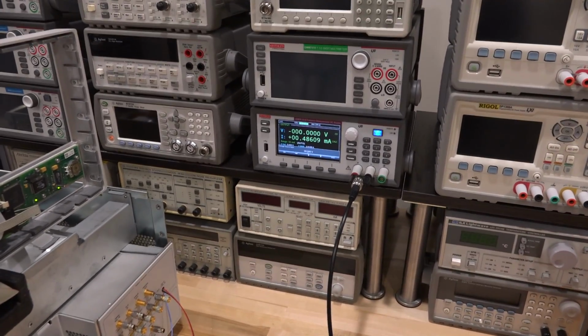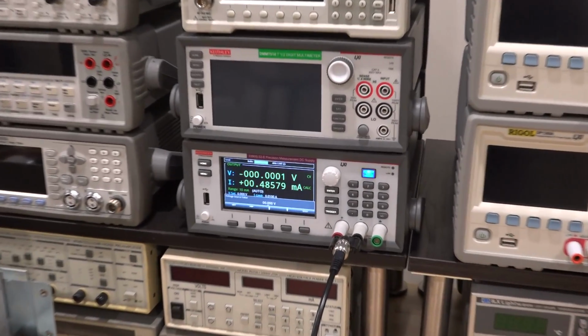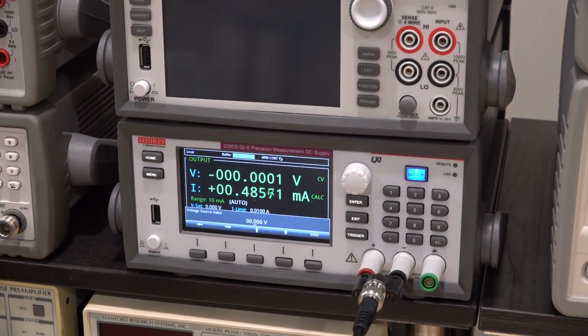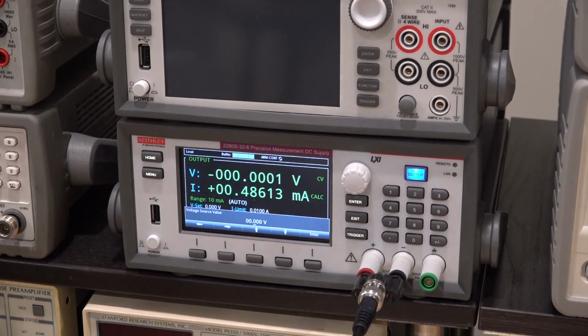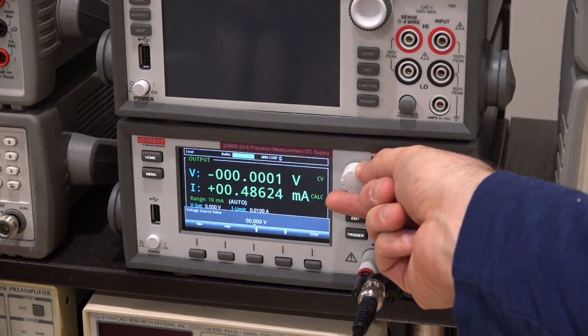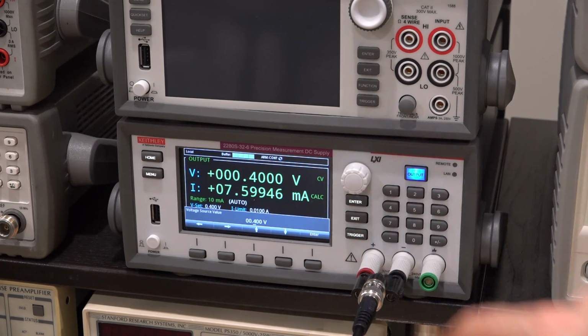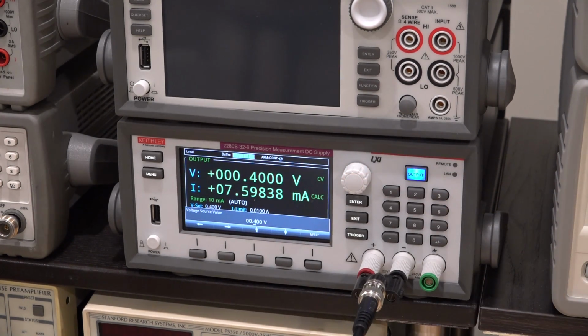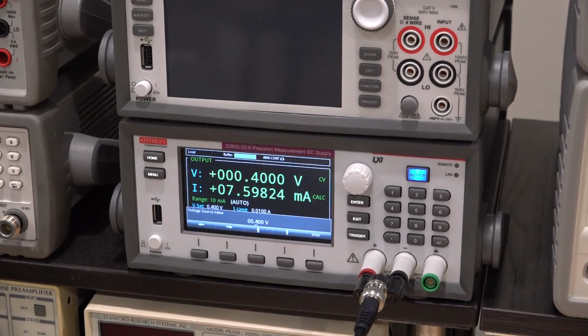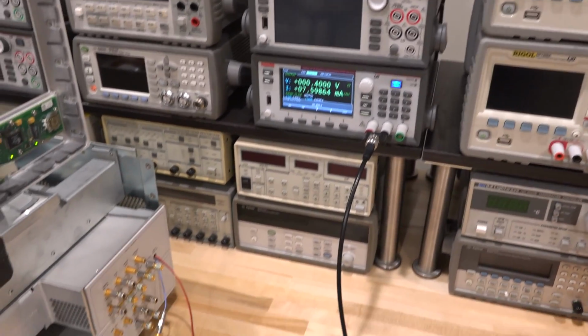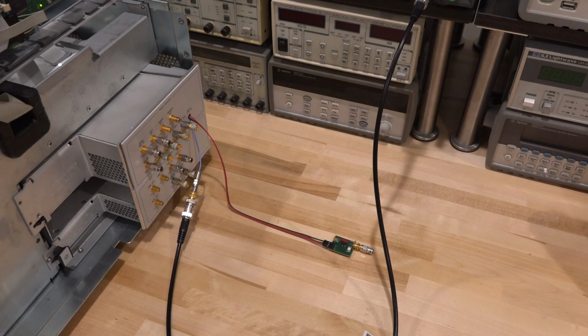If I go ahead over here and apply a positive voltage very carefully and with very little voltage, with current limited into the port, so let's go 0.1, 0.2, 0.3, 0.4 volts. It's drawing 7.5 milliamps into the port itself. This is a really drastic measure. I don't really recommend typically doing this. And I'm going to go to the instrument, and I'm going to go ahead and ask to enable, and guess what happens? The error actually goes away.